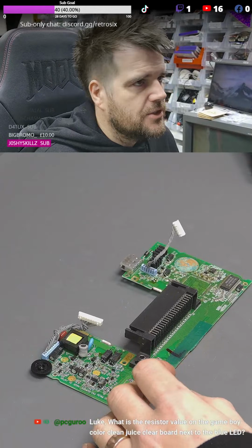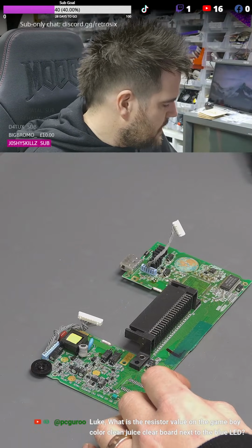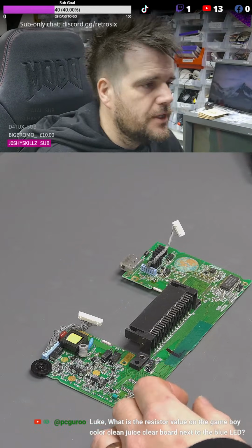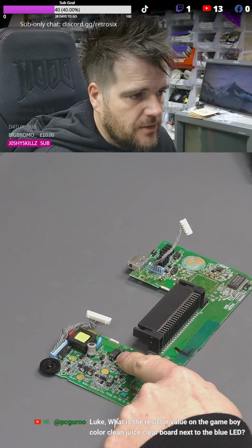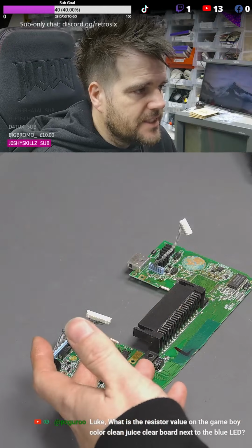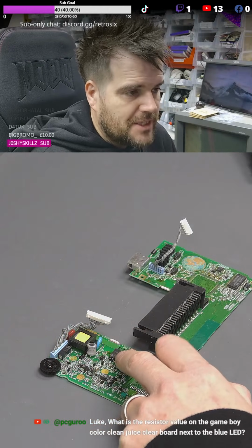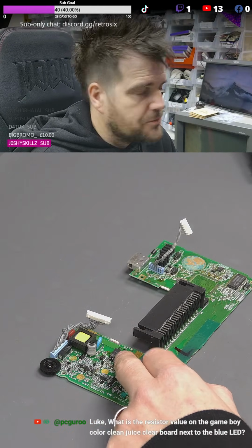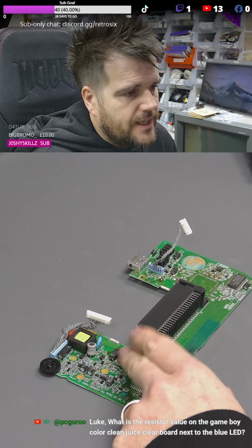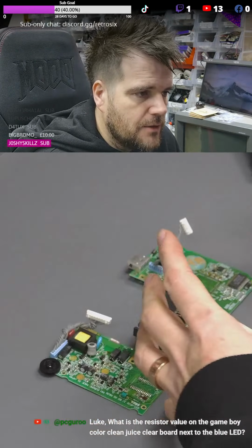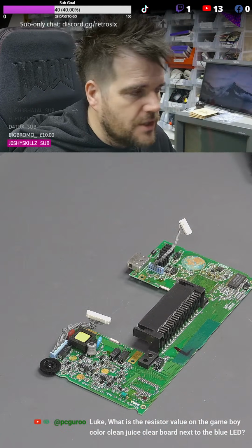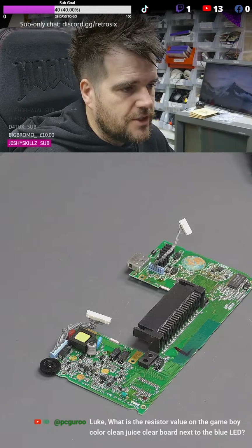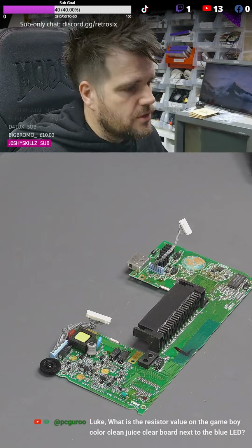So there's various kinds of shorts. We'll cover the exact ones in a minute, but a few that you should know of is when things short out, say capacitors like these start to fail. What happens is they get a lower resistance; basically capacitors should have no resistance when it's a DC measurement. When capacitors start to fail and internally short, they start getting a lower and lower resistance. So like a kilo ohm, then 100 ohms, then 50 ohms. These are just known as shorts. So these are normal shorts, like component failure shorts.